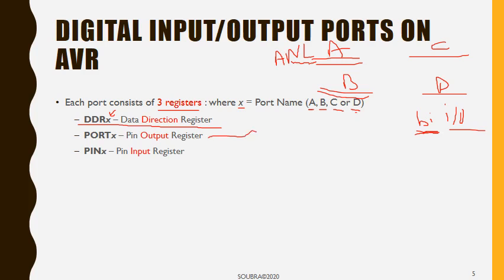And then we have a register where we write the output data to, and this is what goes outside. Let's say that we're dealing with port C. So we've chosen a particular pin on it as an out port, and then the data that we need to send out will be on that particular pin, using the PORTC register.